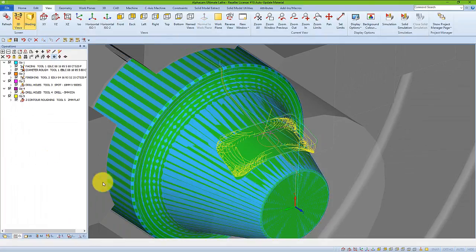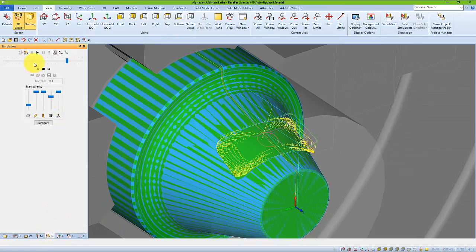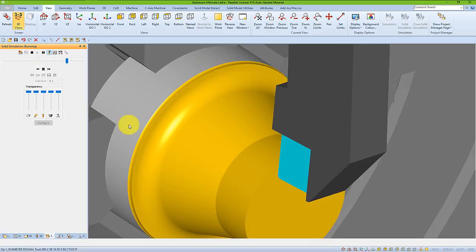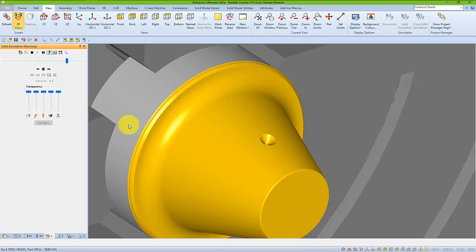So now that's updated, let's go look at the simulation again, and we'll get to see how this has modified the machining. So we now see that the tool actually goes down the hole and it's not machining all the area inside it. It started within it and then works its way outwards. So we've removed all of that fresh air machining that was unnecessary.